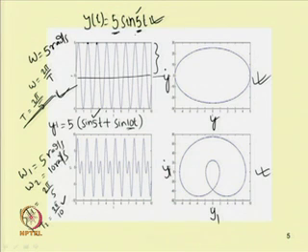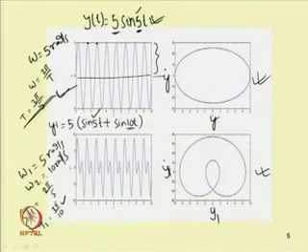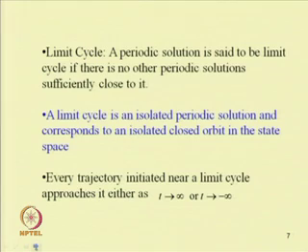Here a simple sine term is given. Similarly, one can take other types of periodic responses which may or may not be harmonic, or we know that if we have a periodic response, we can convert it to that of a harmonic system. So, this is the MATLAB code written for plotting the previous curves. Here, by simply taking different times, one can find the displacement and velocities and plot the response curve.